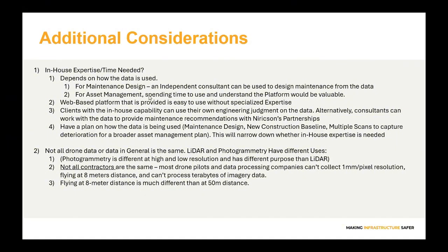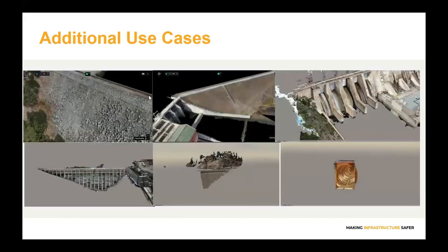I would also say not all contractors are the same. Not all drone pilots are the same. There's a saying in the industry called a weekend warrior, where people go out and fly drones just for fun, and then do commercial flights on the side. Not all contractors can collect 1 millimeter per pixel resolution and develop these types of models that you're seeing here. And it's quite challenging to process that many terabytes of data. So just keep that in mind when you're selecting contractors to do this type of work.